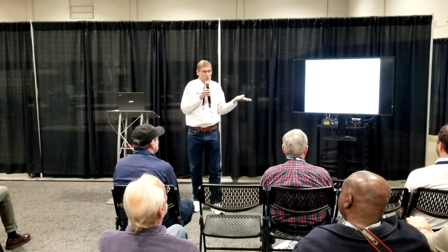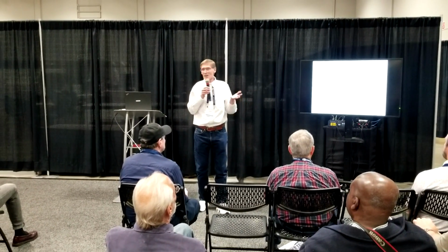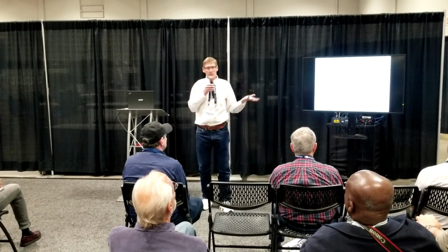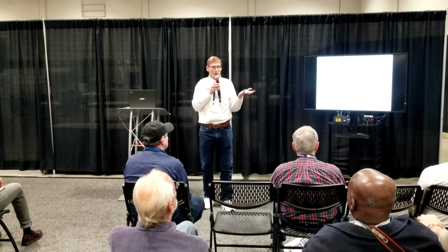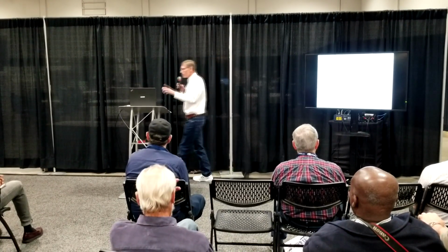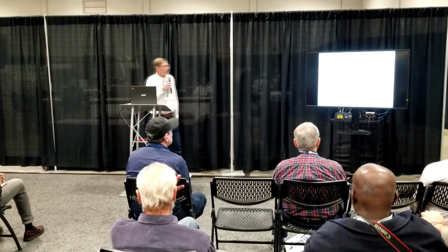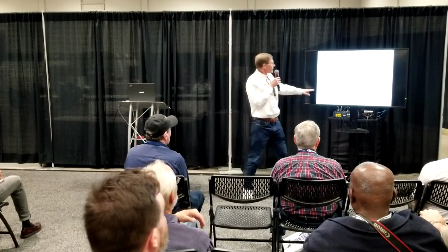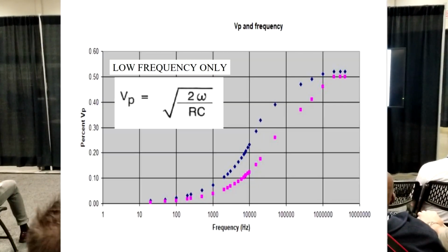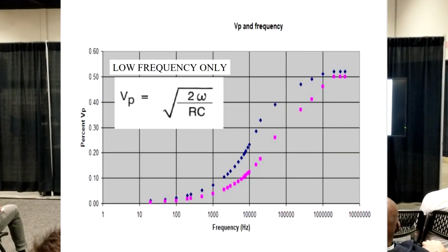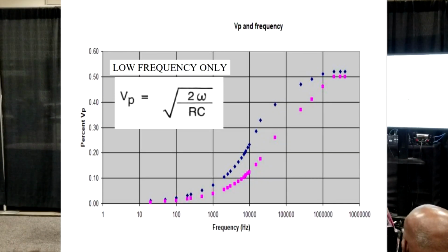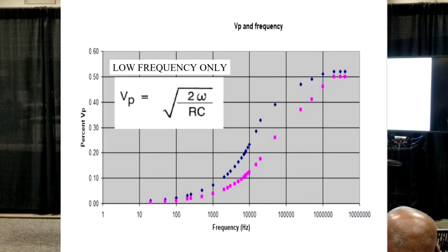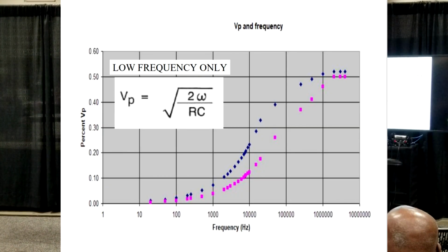It's not the same. Why is it not the same curve? Because it's a different kind of conductor. If I put gold in there, silver, aluminum, you will see different shaped curves based on the characteristics of that metal and how it behaves. Now let's cheat a little bit, or uncheat the curve, and look at what it's really telling us. This is RF up here. Something I want you to notice: people say, well, if that's RF, how come the velocity of propagation is so low? It's 50% of the speed of light in a vacuum. Is that a problem? Well, it's not a vacuum, okay?